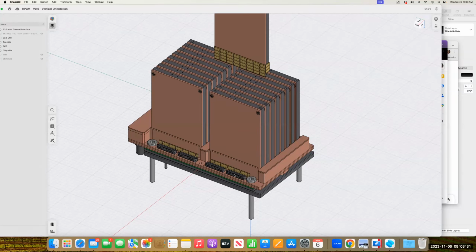You should be able to plug a TE cable into a Molex 4C connector, I'm assuming. But as long as any features we put into this, like the latching mechanism, work with all of the implementations, we need to write the spec, and the specs need to be open. In terms of how the connector is designed, if connector A has much better signal integrity than connector B because it contains special IP from one of the vendors, then that's fine.